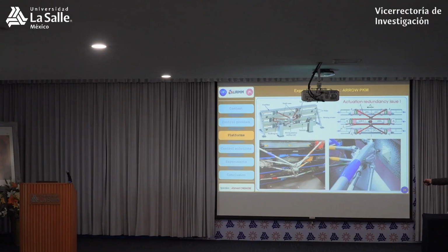Look here. The moving platform has 4 degrees of freedom: X, Y, Z, and 1 rotation. So we need 1 more degree of freedom. How can we get it? Look here, this is a turntable. We have a motor here, and the piece will be fixed here, and we can rotate the piece. So the fifth degree of freedom is here outside. And the parallel platform here has 4 degrees of freedom: X, Y, Z, and the rotation, and then the second rotation will be here. And the rotation of the tool, this degree of freedom, we remove it. So we have 5 degrees of freedom.